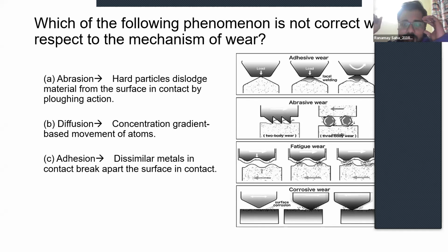At some point, these parts come close, undergo plastic deformation, their shapes change, and they come in contact with each other. Initially there is a clearance gap, but with an increasing number of cycles, such deformations happen and they come in touch, and this type of fatigue wear happens.